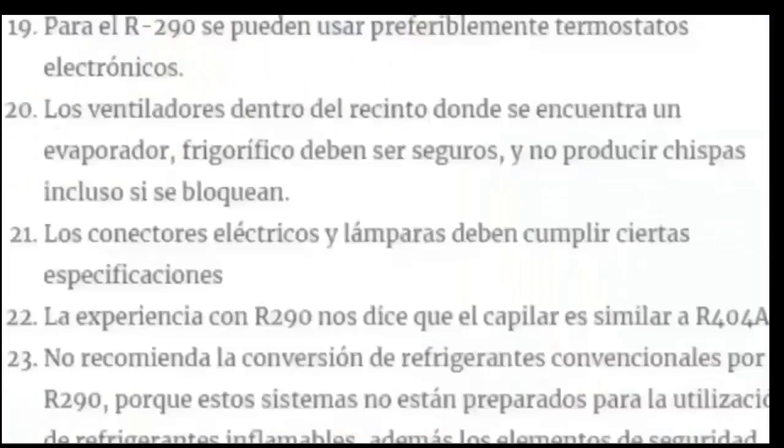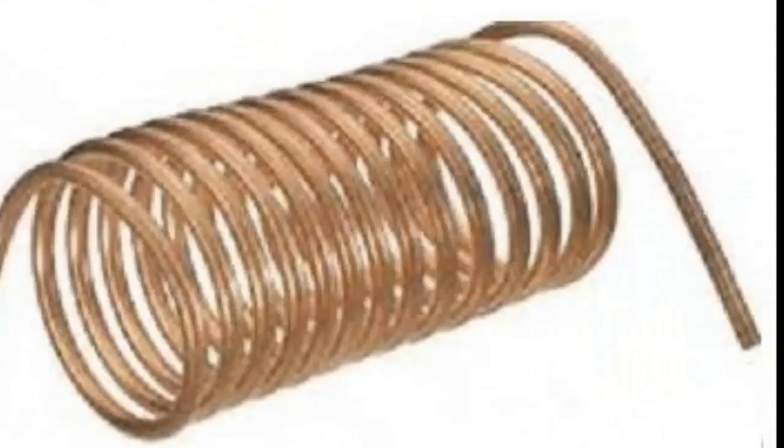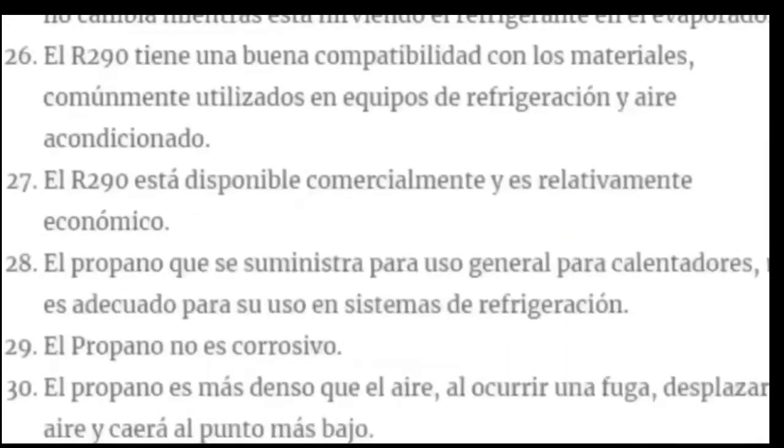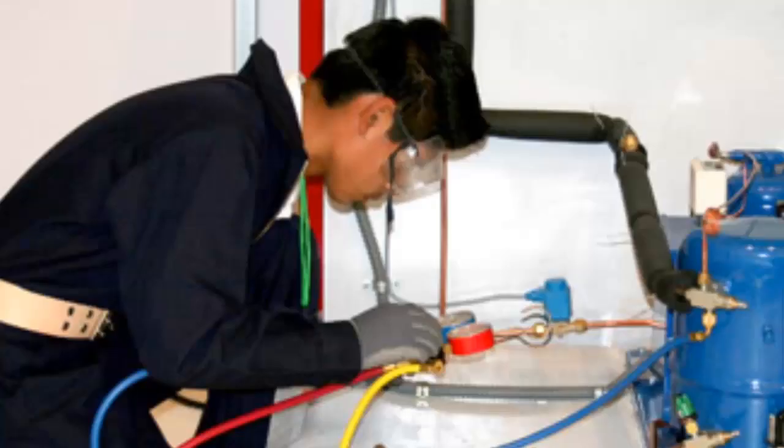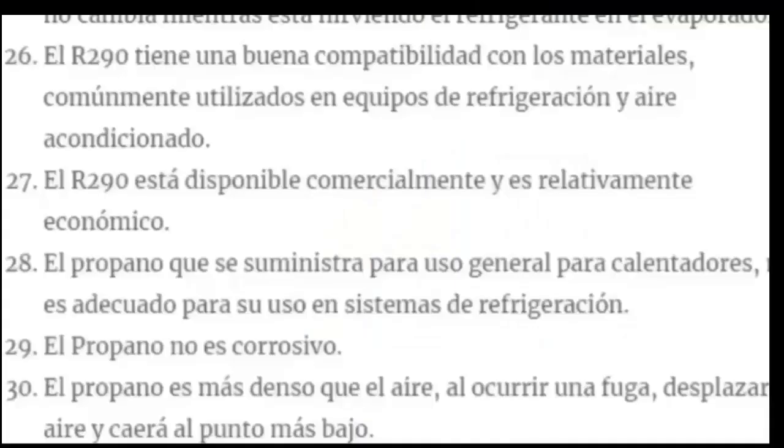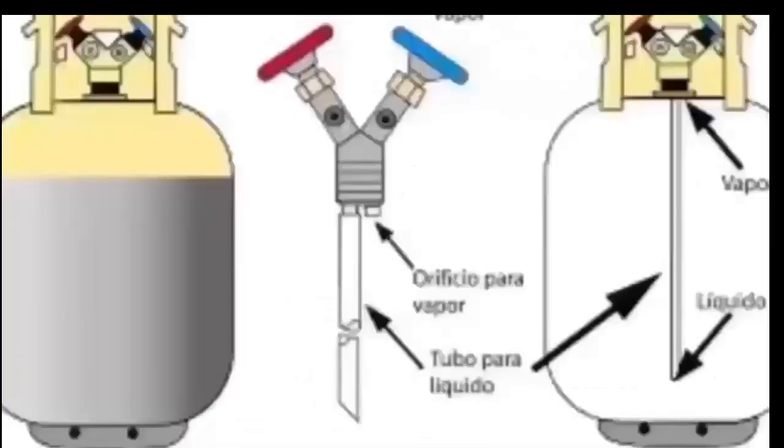22. Experience with R290 tells us that the capillary is similar to that of R404A. 23. The conversion of conventional refrigerants to R290 is not recommended, because these systems are not prepared for the use of flammable refrigerants. In addition, the electrical safety elements do not comply with the necessary standards. 24. The charge of R290 can be carried out in the gas or liquid phase.